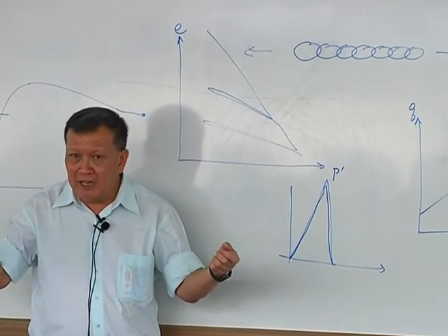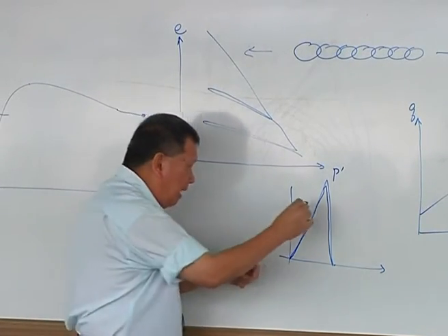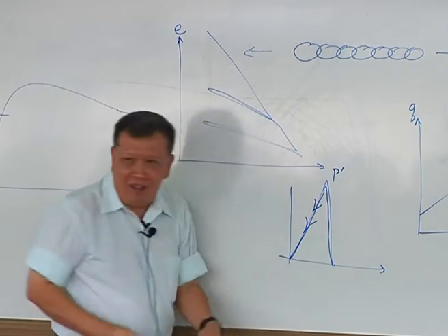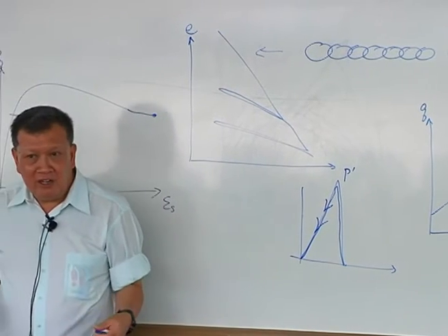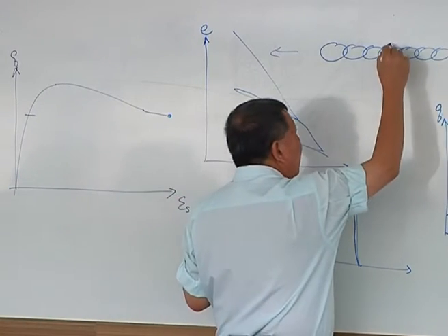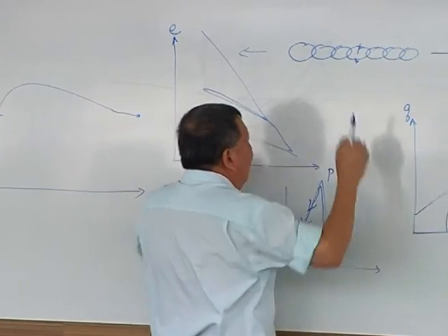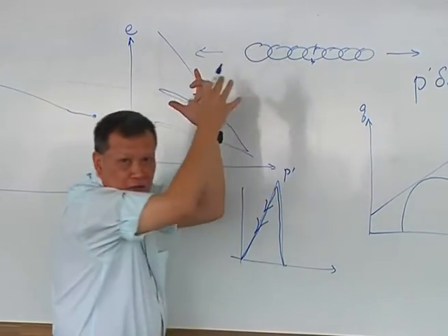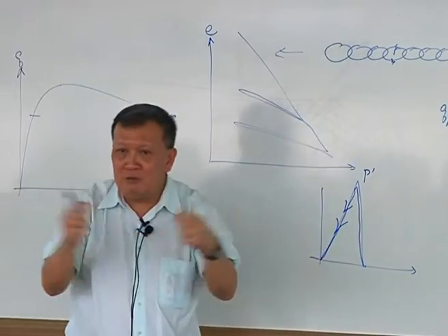What about the rest of the links? They will immediately unload back. They go elastic unloading. Okay? So basically, supposing this is the weak link, it will go, and then the rest will just unload, because they can't transmit the stress across.